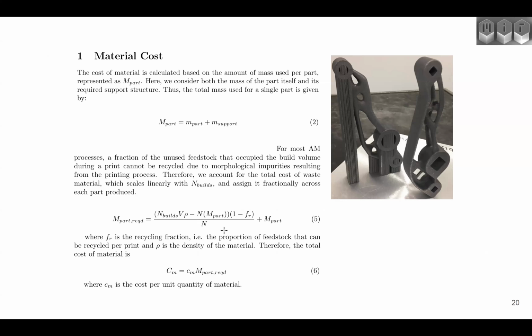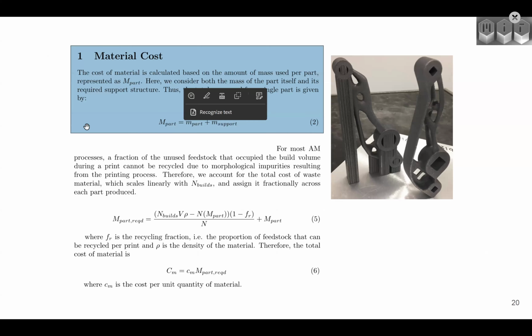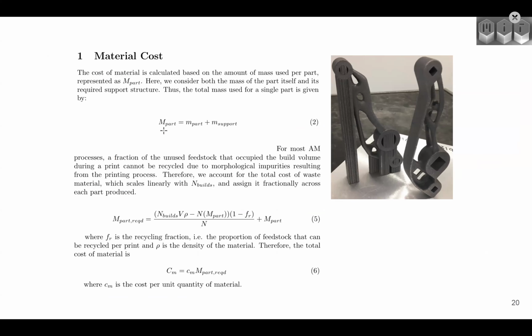So now getting into the fixed versus variable cost discussion, the material cost per part in the first equation, this one up here, is a variable cost. That scales with the number of parts. Material losses we can treat fairly simplistically and say X% of our total powder volume, or whatever the feedstock is, is going to be lost per print.